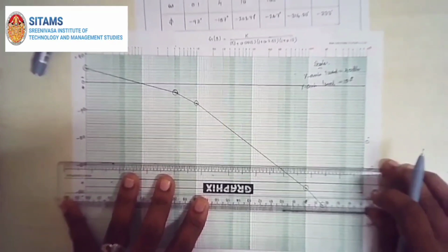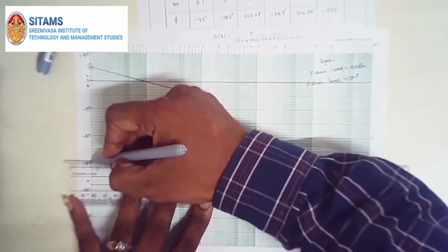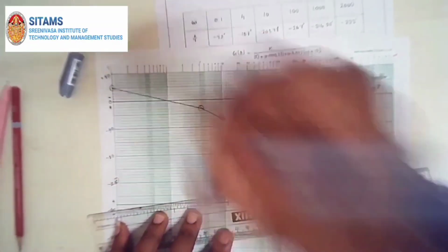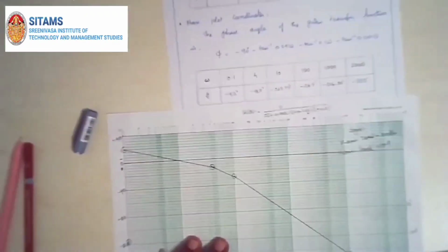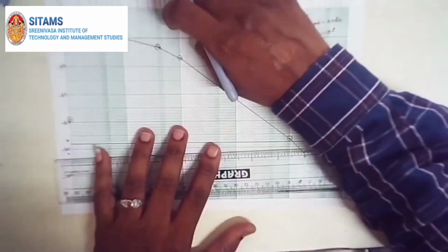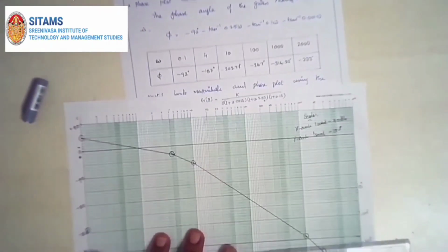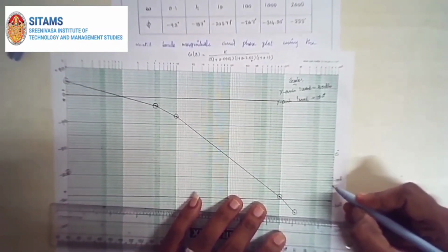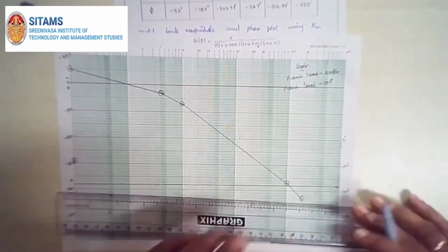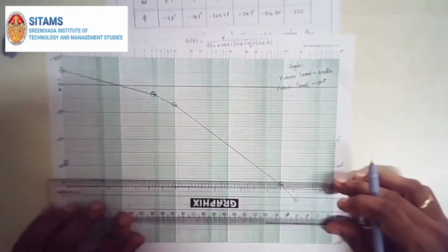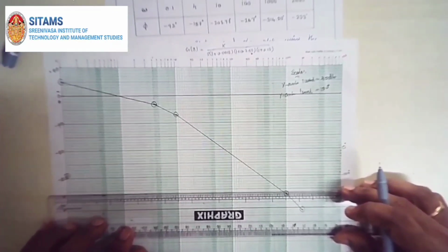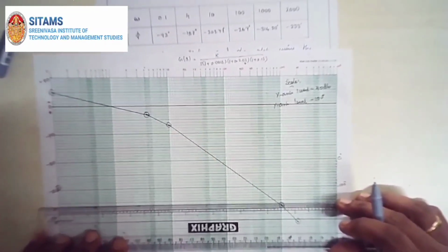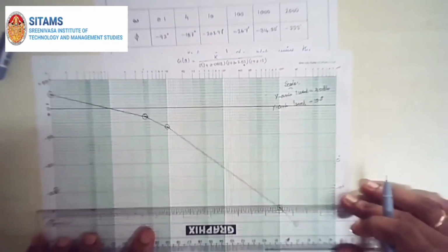So I kept it, and the corresponding frequency is 0.1. So 0.1 radian is the first line. So I have plotted my first coordinate. Then the second one is minus 157. So I will take minus 160. Rounded, you just round all the values of phase angle so that it will be easy for you to place the plot. So minus 160 I will take. So this is minus 110, 120, 130, 140, 150, 160. So I want to keep the scale along minus 160. So placing your scale plays a vital role when you are sketching the Bode phase plot. I kept it exactly at the minus 160 line.